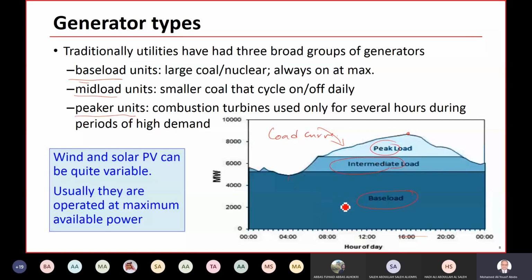In this case, you distribute. For example, we will cover the base load with hydro if we have it, and the nuclear. Okay, so this will cover some of the thermal generators also. So this will cover the base load. If we need more load, then we will commit some of the thermal gas turbines.